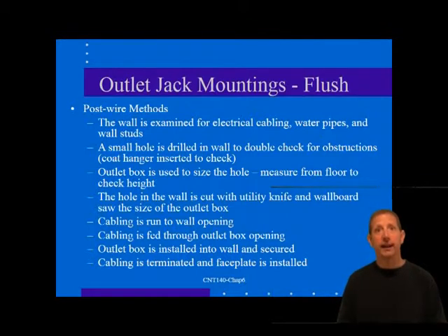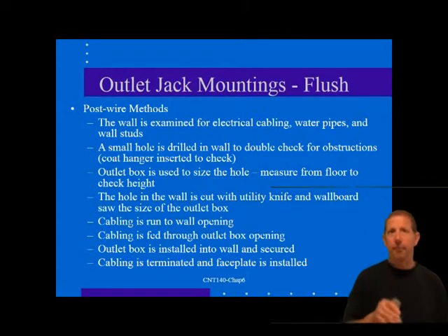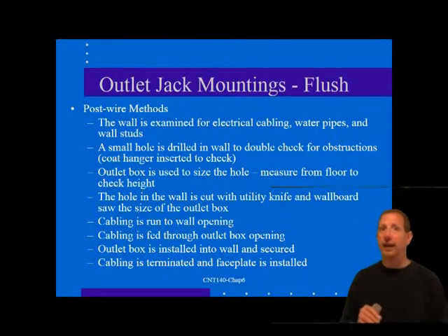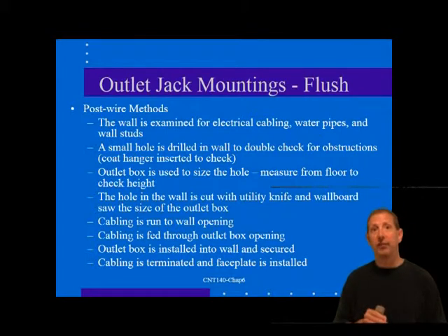Again, if you're planning on a Cat 5e or 6 installation, be careful not to put sharp bends or kinks into the cable. Tie wrap may be used sparingly, but should not be overly tightened. You should take care when running your cable into an outlet box so that you don't slice through the cable jacket. Metallic boxes often have sharp edges as a result of the way they are manufactured, and these sharp edges can cut into the cable and short some of the wires.